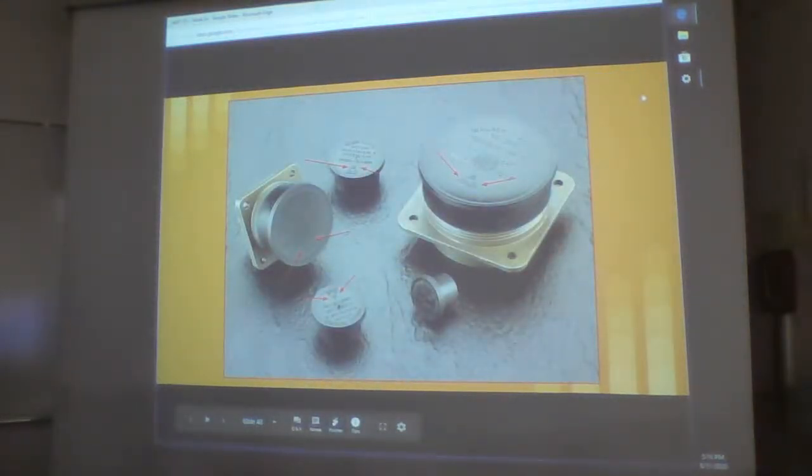So I blew up that same picture to show you guys these little red arrows are pointing at this little triangle symbol. It's a little hard to see, but you can probably see it. All of them have them if they are ESD caps. It's like a little triangle with a hand, and it's crossed out because that's the symbol for ESD. We don't want your hand touching the mating pins in here.